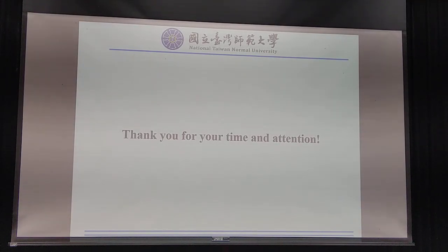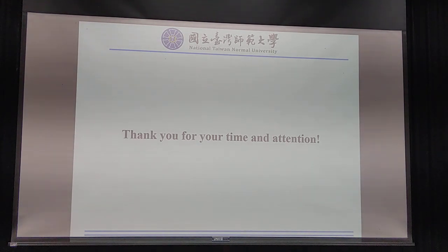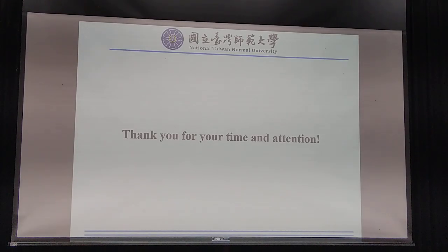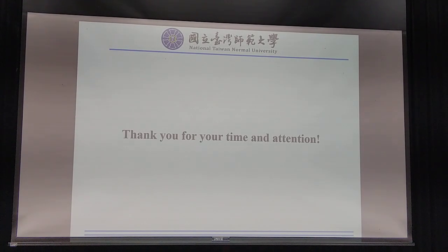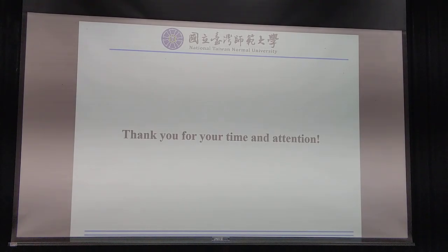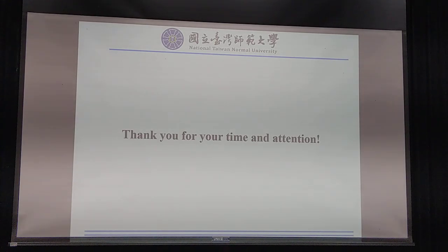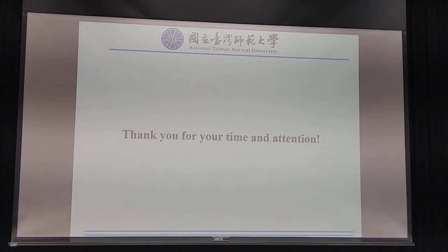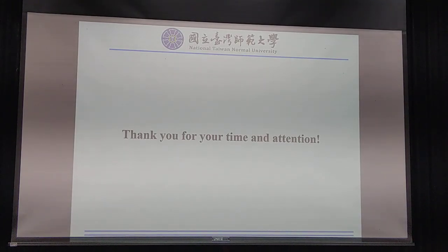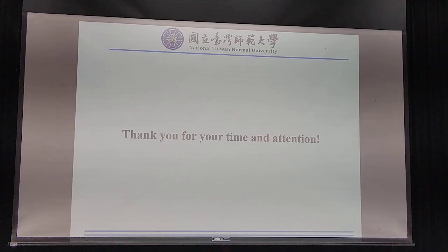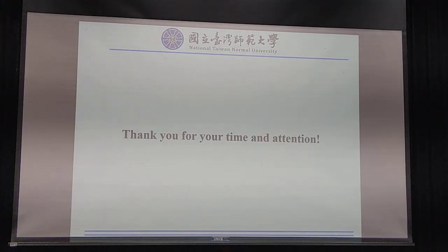Standard MPC lacks the ability to foresee the trickle charging function. It might allocate high power to a bus over its 80% SOC limit. Only small amounts are then cut off by the trickle charging limit, leading to wasted capacity. In contrast, our PCMPC incorporates a sigmoid-based power limit directly into the prediction model. This allows the controller to predict the bus's entire trickle function and proactively reallocate that power to other buses that still have high demand, thereby improving the station's overall power utilization.